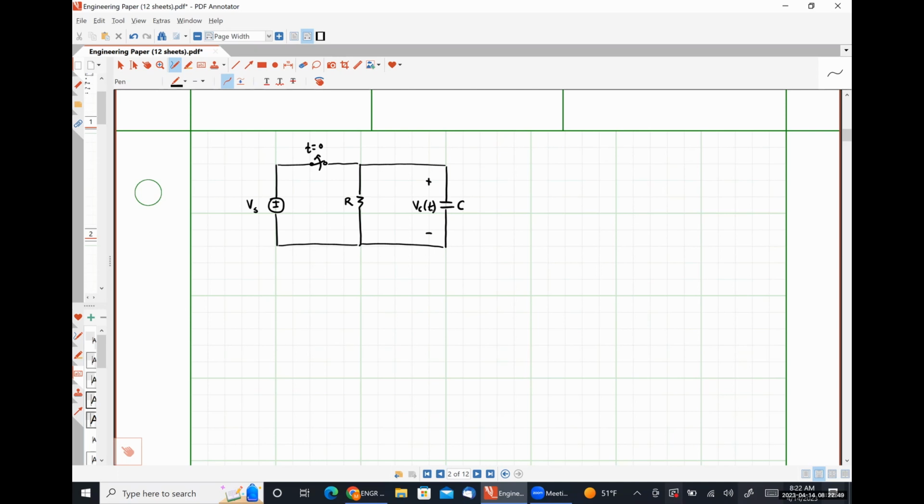No. No, so the type of source that we are using to excite the system at t is equal to 0 minus and before literally does not matter. We're only concerned with what the shape of the voltage across the capacitor waveform is going to look like and what the shape of the current flowing through the inductor is going to look like. Those elements don't care what they're connected to.